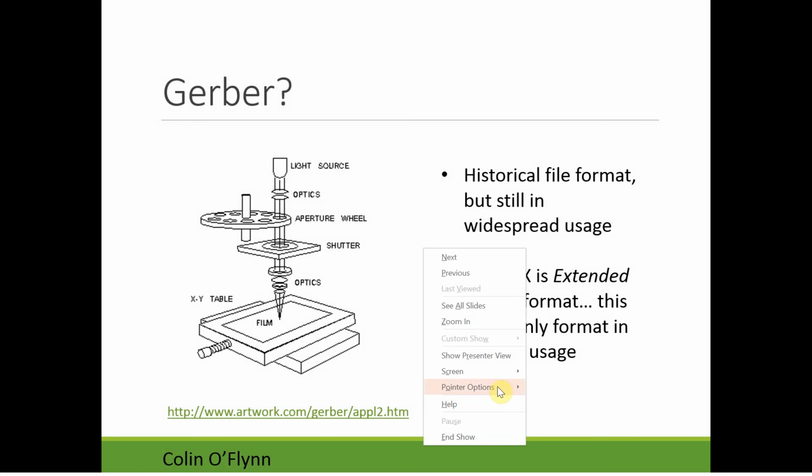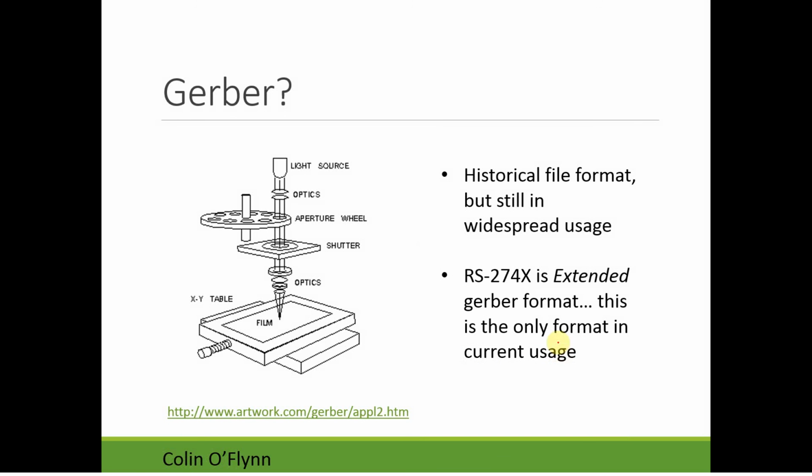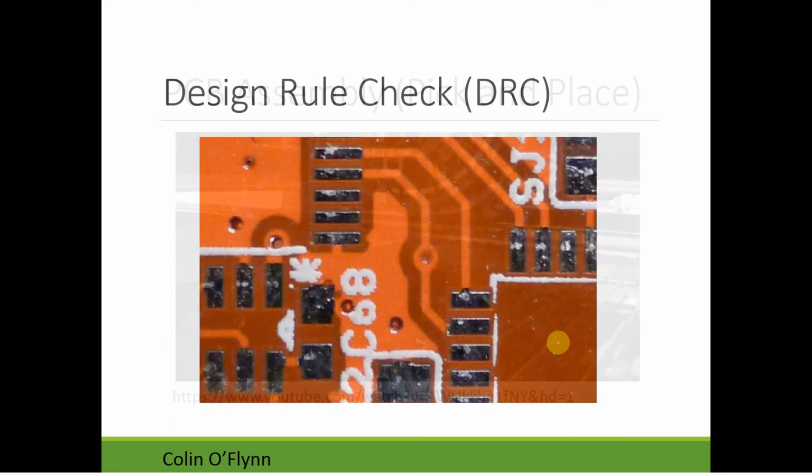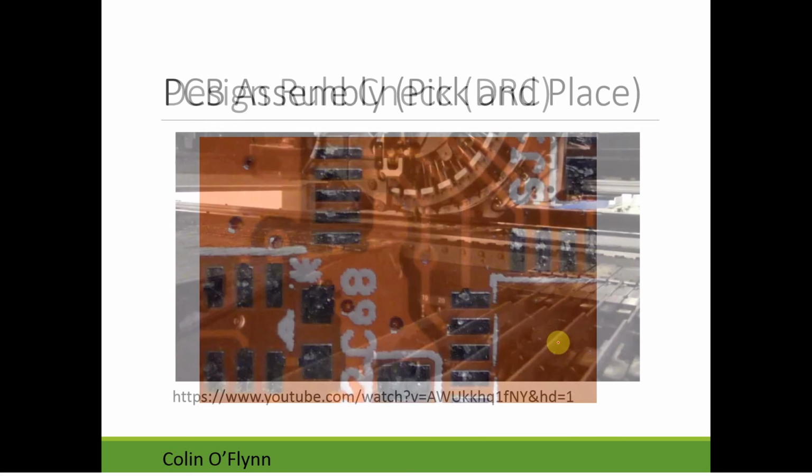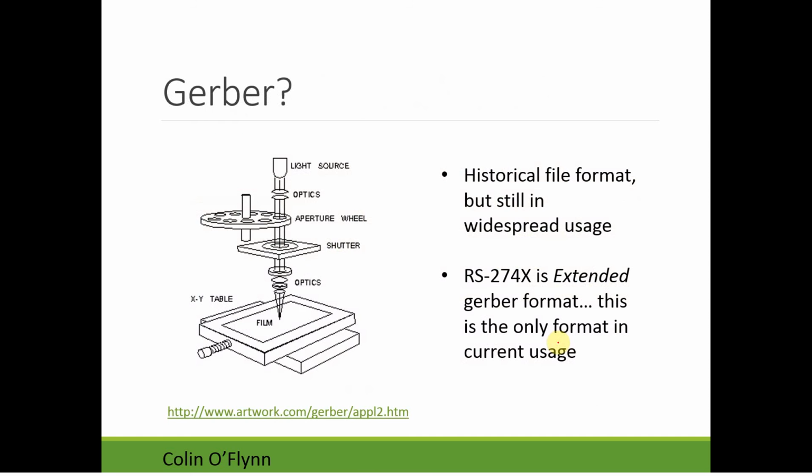But anyway, the other thing you'll need to know about is, so you have a design, you want to get it manufactured. How do you do that? You'll see everywhere this reference to Gerber files, and this is just a historic file format that's been used in circuit board layout, but it's still in very widespread use, and this is what most of your designs will end up being submitted in.